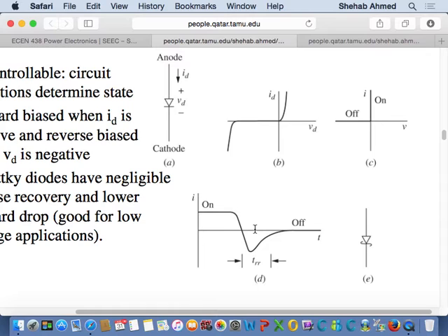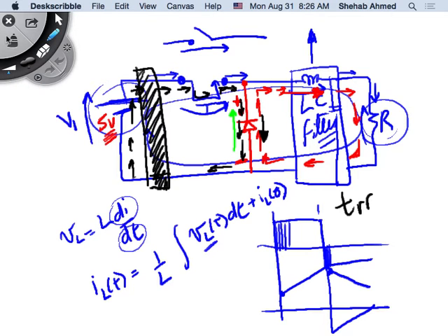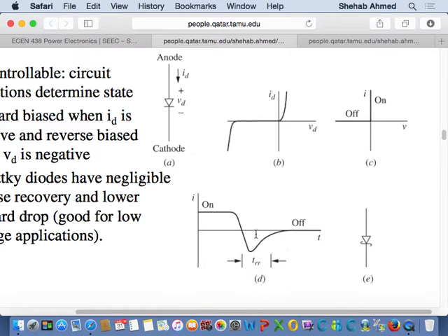Okay, so because I have to live with it, it's actually current flowing through my circuit, and we saw that this current is actually flowing through where? It's actually flowing through my MOSFET and through my diode, right? And both of these devices also have voltage drops across them during that period of time when they're conducting, right? That means there is power loss. So it's really a pain that I have to live with something like this, and it's not something that I really like, and it's not very useful for my power conversion process.